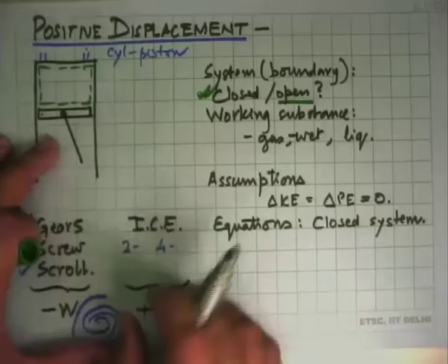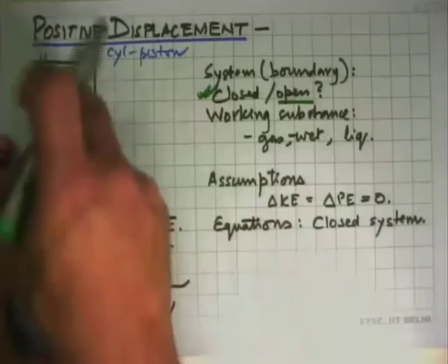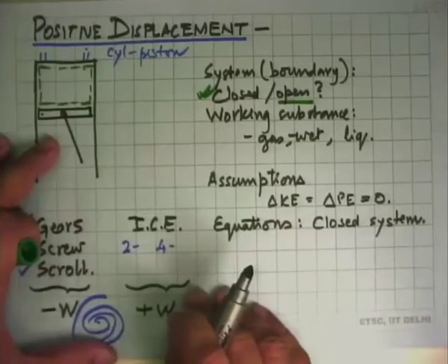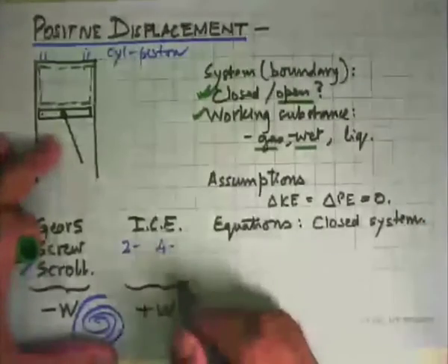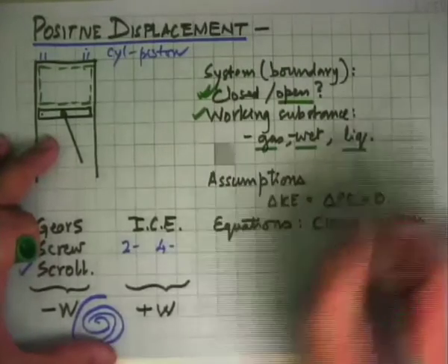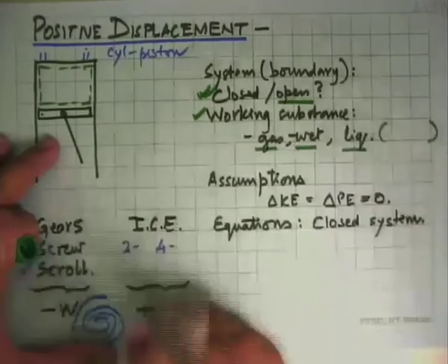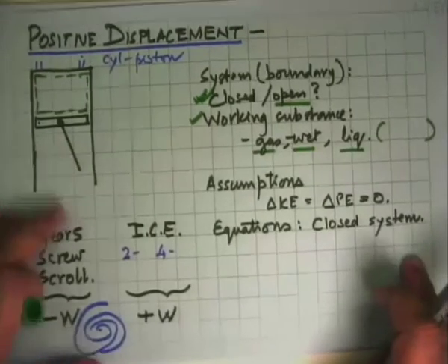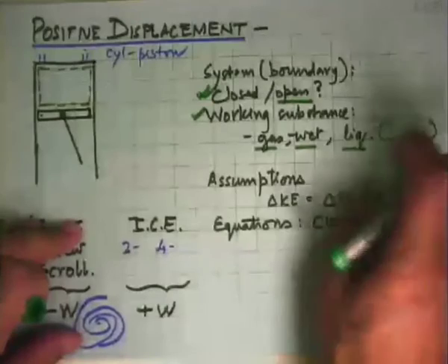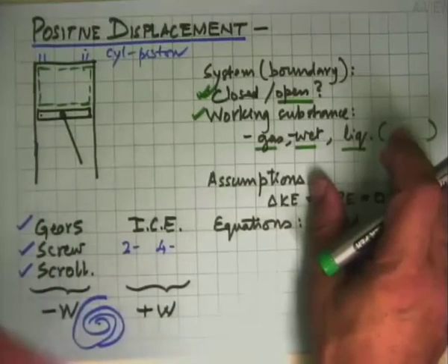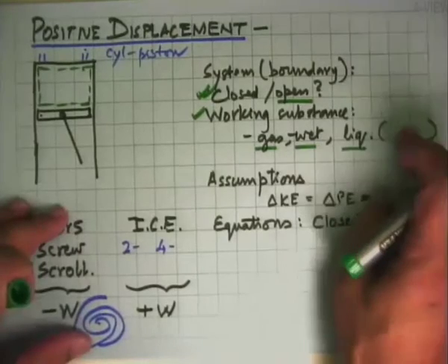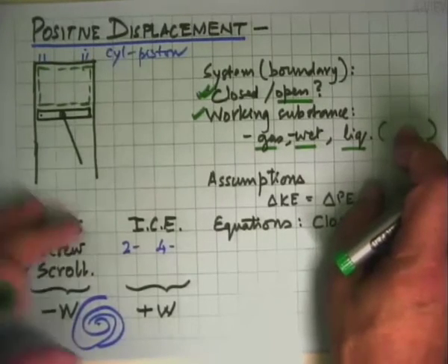Once we define that it is a closed system, the next thing we have got to see is what is the working substance in this. And so we write down that the working substance could be a gas, or a wet saturated state, or a liquid, and we write down the name of that: nitrogen, oxygen, or butane, whatever it may be. So we know that in subsequent solving, when I need to get properties, which material is there for which I should get standard data.